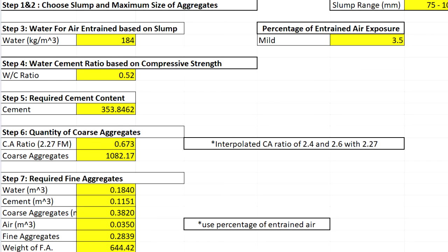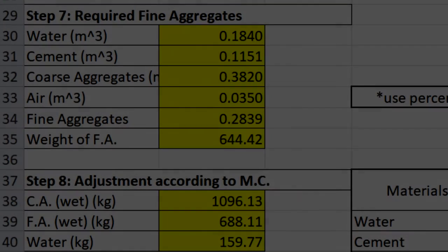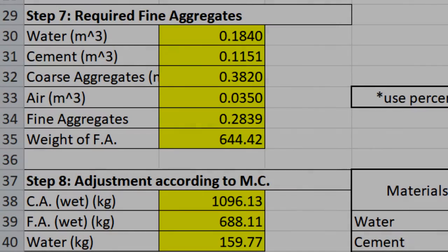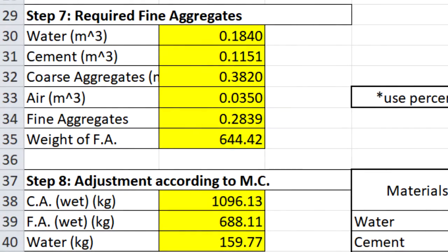In this experiment, it is quite important to consider factors such as the water-cement ratio, volume of water, aggregates, and cement. The common established values in the mixed design of concrete are the size of the fine and coarse aggregates, unit weight of coarse aggregates, bulk-specific gravity and absorption of aggregates, mixing water requirements for a given type of aggregates, relationship between strength and water-cement ratio, and specific gravity of cement and pozzolan.